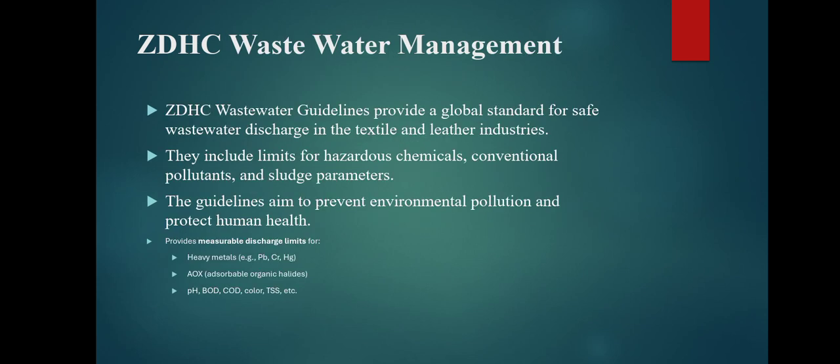ZDHC Wastewater Management. ZDHC developed the wastewater guidelines to set the global standards for how factories should manage and treat wastewater. What do the guidelines cover? The limits for hazardous chemicals like heavy metals, lead, mercury, chromium, and the limits for conventional pollutants: pH, biological oxygen demand, chemical oxygen demand, color, and total solids, and rules for safe sludge disposal.